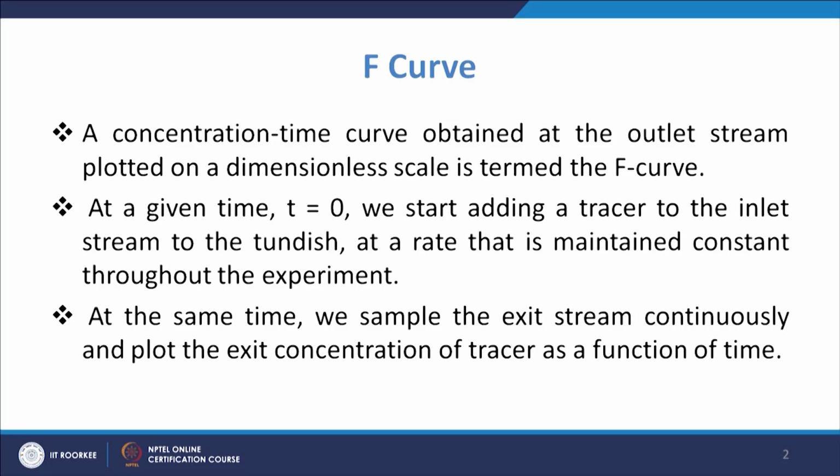As we see, if you go for the step input, then we get the F curve. The F curve is nothing but the concentration time curve that is obtained at the outlet stream plotted on a dimensionless scale. So, then it is known as the F curve. On the y axis you have dimensionless concentration, and on the x axis you have dimensionless time.